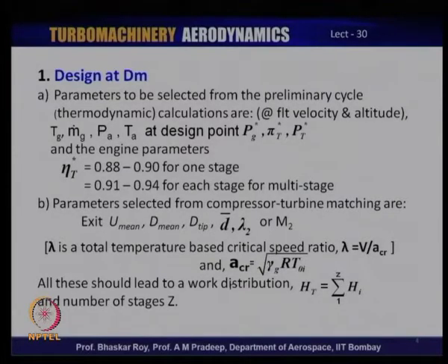You remember the amount of work done in a turbine stage is substantially more than that of an axial flow compressor stage, and as a result the number of axial flow turbine stages is normally far fewer than the number of axial flow compressor stages. Hence a little bit of extra work more or less would have to be accommodated within the integer number of stages that are possible.